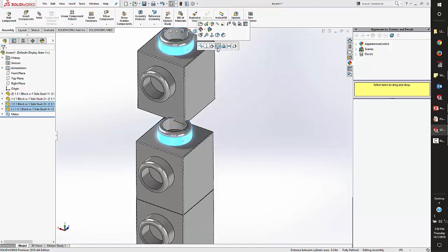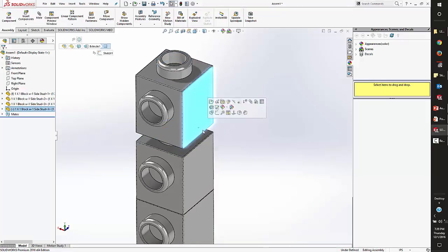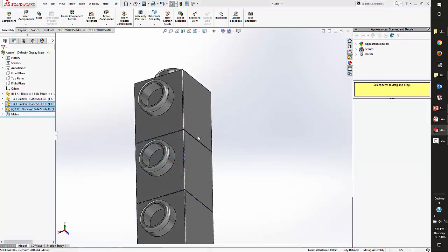So the reason I like it is because I don't even have to click it. In fact, if I click off of it, I'm going to hit these 2 surfaces again. What I have done is I turned one of my extra buttons on my mouse into the Enter key. So leaving my hand still on the mouse, I can click that button. Now that's concentric. I can click the 2 faces, hit Enter, click the 2 faces, and hit Enter. And now I've been able to put those mates in pretty quickly.